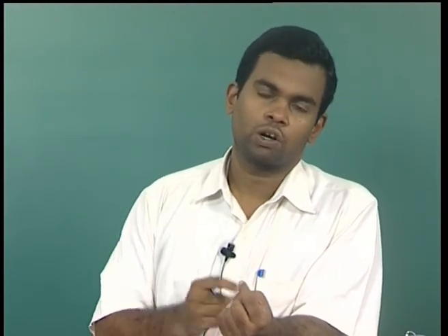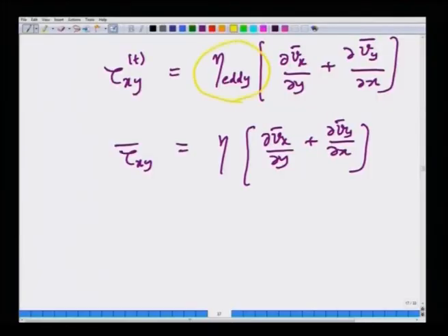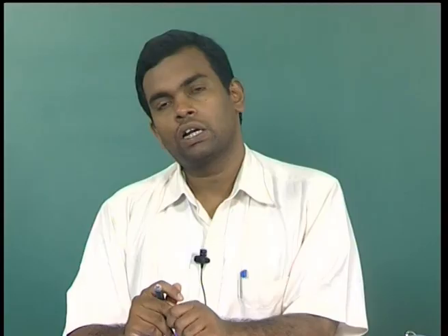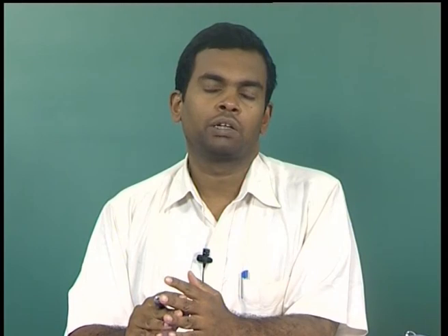So, clearly the eddy viscosity cannot be a constant, it has to be a function of position in order to correctly describe the physics of fluid turbulence. Okay. So, essentially we cannot say that the eddy viscosity is a constant, because otherwise it becomes a trivial problem. So, we have to bring in spatial dependence of the eddy viscosity on the various spatial coordinates. And we are saying that all of turbulence can be described by just one function. Okay. Essentially, it is a function of spatial positions, but that is certainly questionable unless it is backed up by experiments.